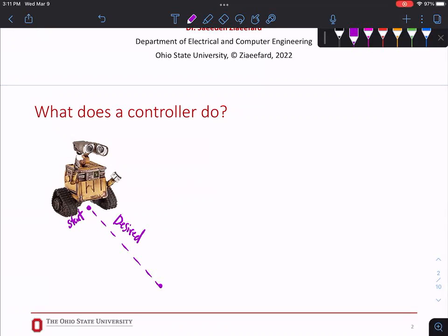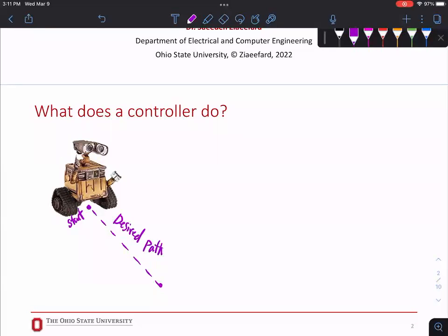It's the desired path, right? It's called the path, and it's going along an axis or direction. This is the x direction. So if everything works and everything is aligned, this robot will go on a straight line, right? Now, due to error in the system or the environment, if there is a bump on the road or something wrong with a subsystem, for example the wheel, this robot might get off the track and end up here, right? This would be the final position.